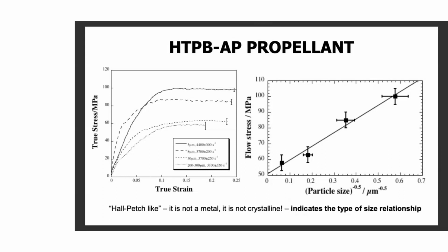So from this, we undertook a further series of studies to determine if it was the size of the filler particles or the distance between the filler particles which was an important controlling factor. The outcome of that was it seems that it is the distance between the particles, so the thickness of the binder, that has a large controlling effect.